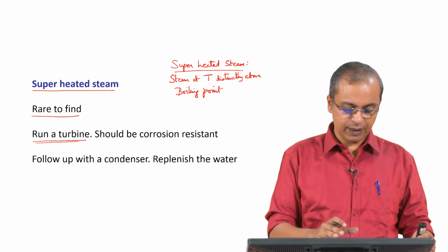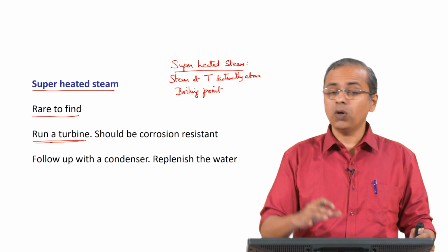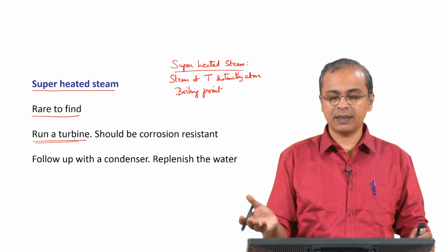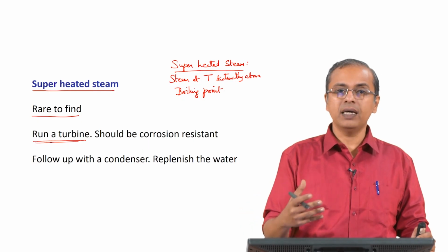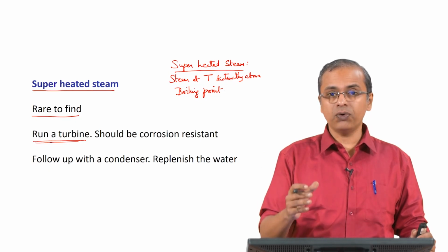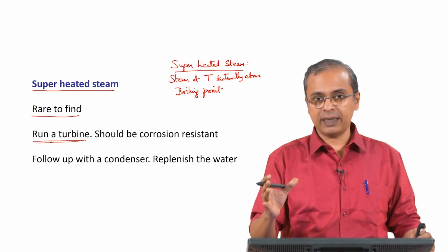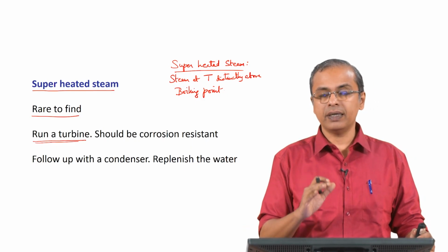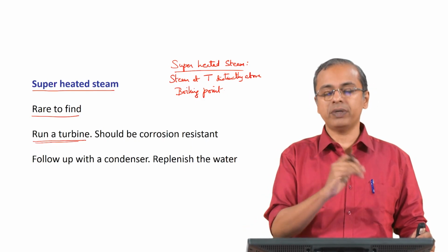Now, in the case of the geothermal plant, what is coming from underground may not necessarily be 100% steam. You may have some other gases in it, you may have even some radioactive material in it, etc. So, therefore, what goes into the turbine, especially under these conditions when you are sending it directly into the turbine, is potentially something that can damage the turbine.